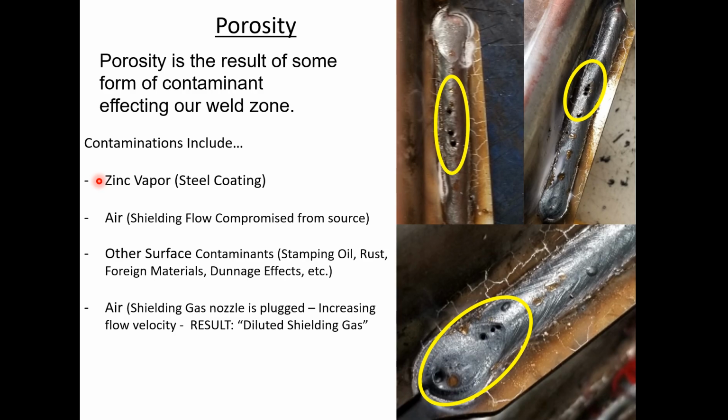But know this: if in your welding process the zinc, and this is all thick zinc that's right in here, gets caught inside this puddle, it can't get out and it will not mix with the welding puddle. When it doesn't mix, zinc actually boils inside the iron of the steel. It boils inside of it and creates a gas, and the gas is captured while the weld material is starting to solidify. So zinc is a very serious issue. We're going to talk about the porosity standards in a second.